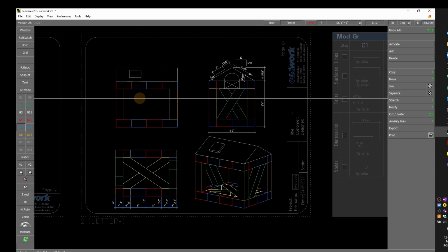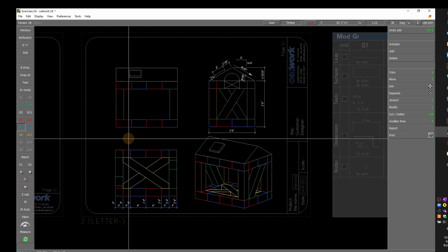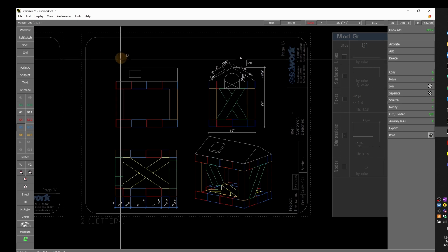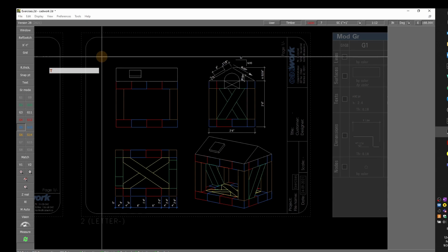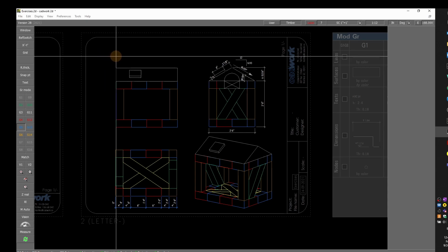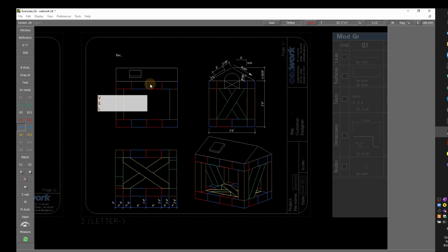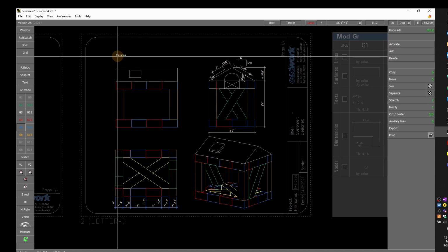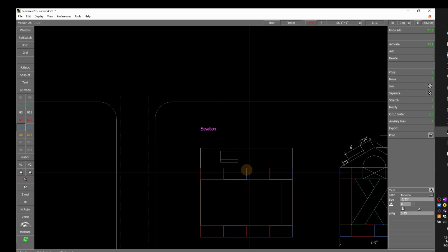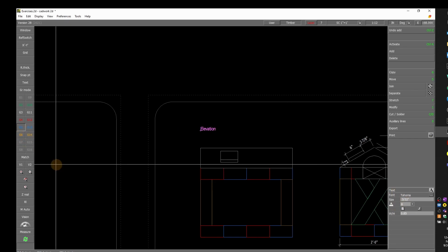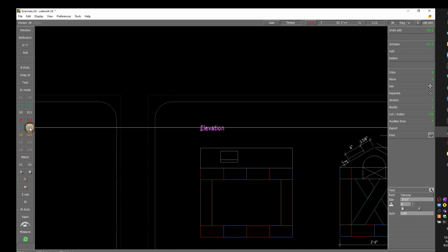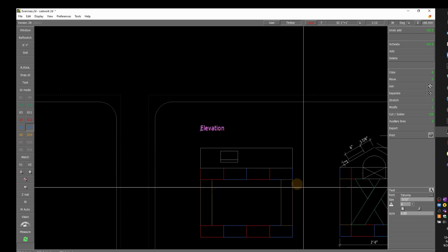So now the next step is to add some text. So I'd like to add a text here. So I press T to add a text, and then I can middle click where I'd like to add the text. So here I'm going to write elevation, enter, and then I can copy this text. So the text is preset because it's the ones set in G5. I could eventually change it and middle click here, and you see it's changing the size.